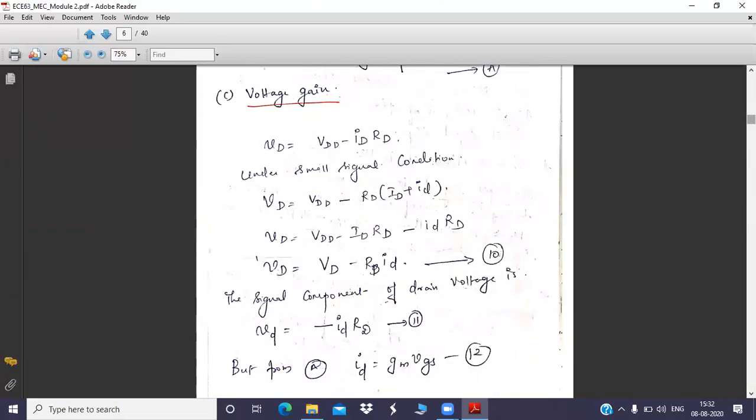Now I would like to complete the voltage gain equation as well today. And you know what gain is? Gain is nothing but the multiplication factor we give for the input to be amplified. Suppose the input is very weak, and you don't have enough strength for that input. So you will amplify that input signal by a particular factor. That amplification factor is nothing but the voltage gain, which is equal to output voltage divided by input voltage. So here we are directly finding the ratio of output voltage to input voltage so that you will get the equation for voltage gain. Understood? So how are you going to find the equation for voltage gain?